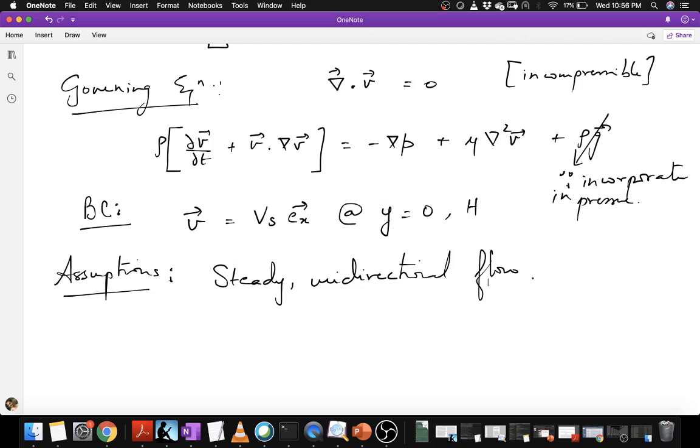What is the Reynolds number and why does its smallness suggest stability of such a unidirectional flow? We will address that in the next lecture, as that also has to do with scaling. Some of you should already know about the Reynolds number. If you don't, just take my word that in microchannels this is a good assumption, and experiments show that the flow is in fact steady, unidirectional and fully developed, that is, it does not change along the flow direction. In fact, you will see that the fully developed feature follows from unidirectional flow, so I don't have to write it as a separate assumption.